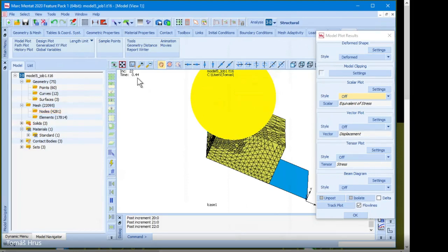That means in the time 0.5, the displacement of the sphere will be stopped and it will be taken back. So we can see that the limit was not taken in account now. Yeah, but I think it's clear what happens if the number of nodes will come to 10,000. Yeah, the adaptivity of the mesh will be stopped, and the rest of the solution will be made with the last adaptivity step of the mesh, and other adaptivity steps will be stopped.